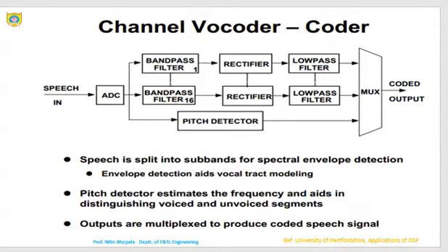The sampling rate for all signals must be above the Nyquist limit. These samples may then be transmitted as a single signal. A demultiplexer circuit on the receiving end can easily separate each signal since it knows the timing of the samples.